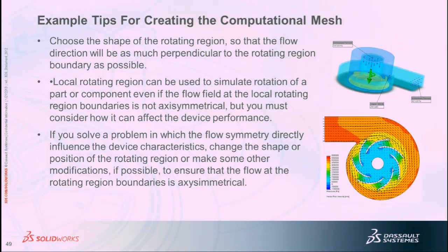Okay, now a couple of other quick tidbits. Another tricky thing, usually, is rotating flow models. Rotating flow models can be tricky just because CFD cannot do moving geometry, and a rotating flow model has spinning blades. So as a workaround, what they use is what's called a rotating frame of reference, where in the actual Navier-Stokes equations, you can add the angular velocity as a body force term.